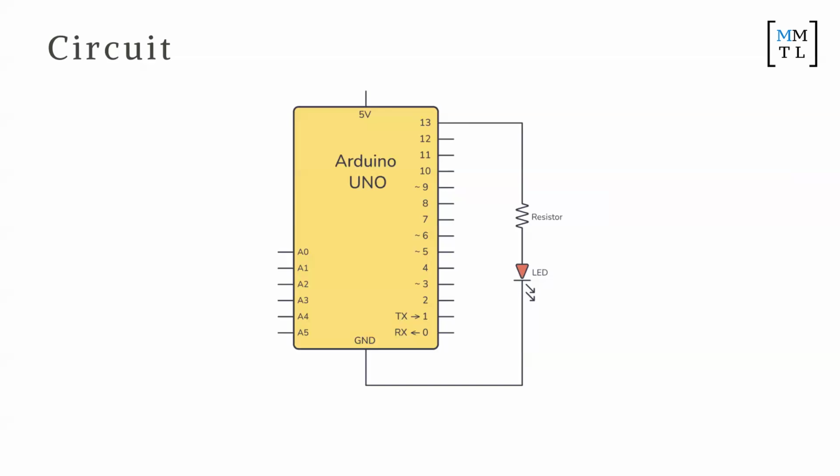So you never want the LED and resistor together in the same row. They should always be in separate rows. How would you fix that?